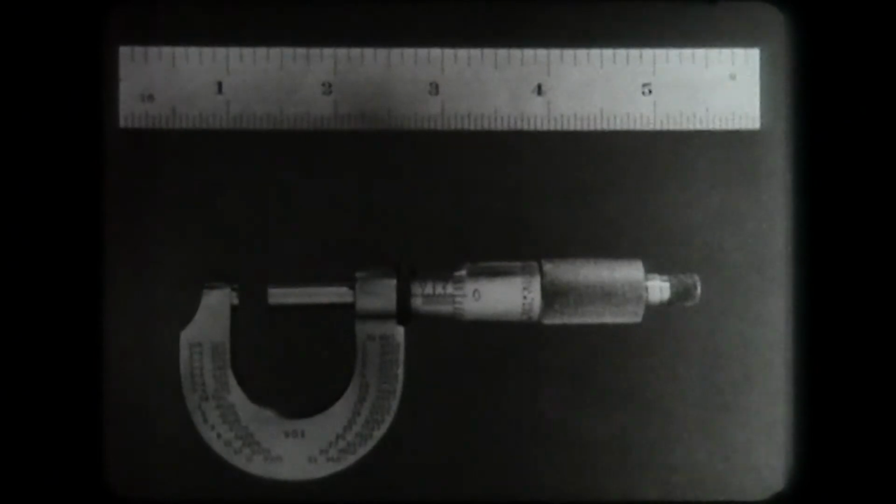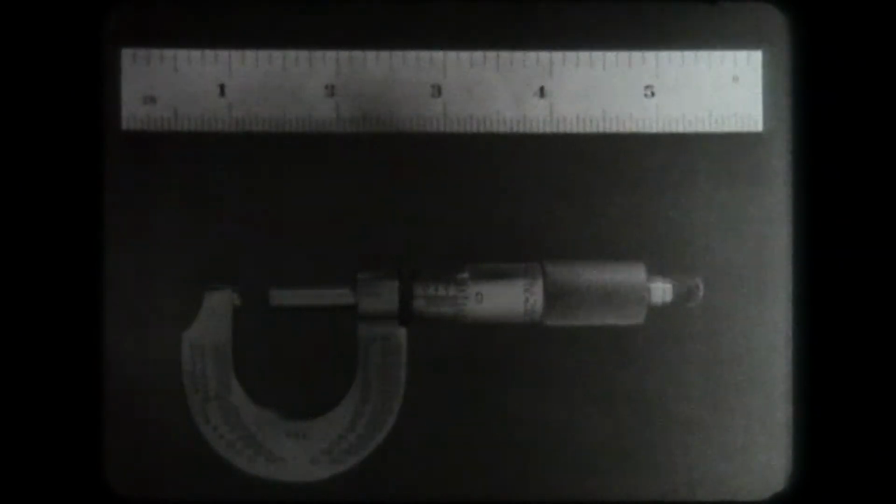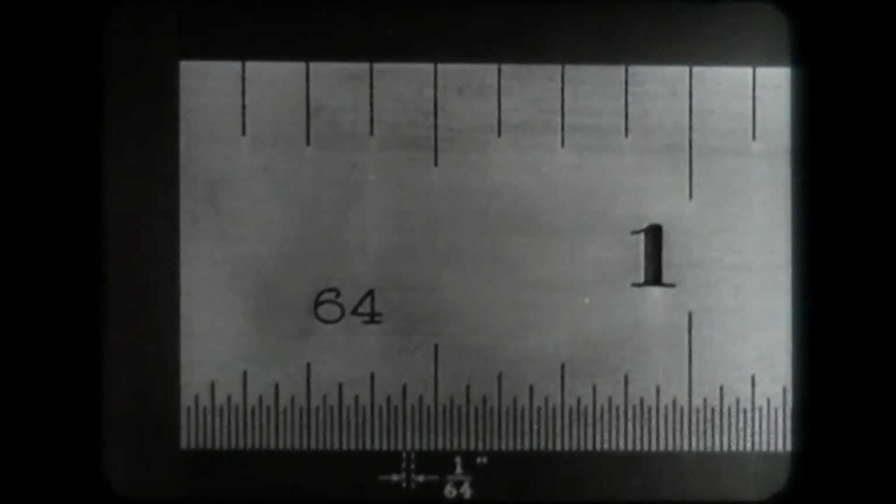The chief difference between the two is the accuracy with which distance can be measured. The steel rule measures in fractions of an inch to 1/64th. One 1/64th of an inch is nearly 16 1/1000ths of an inch, written in decimal form as 0.015625. Measuring in distances as small as 1/1000th of an inch or less is done with the micrometer caliper.